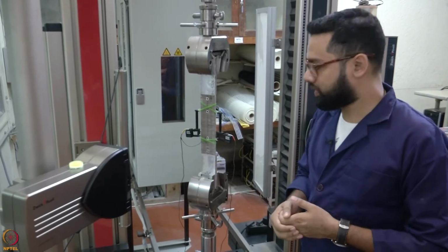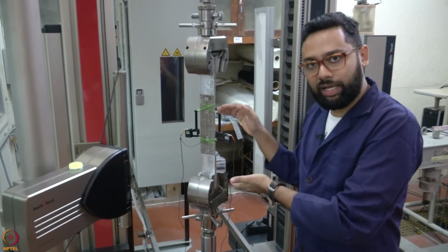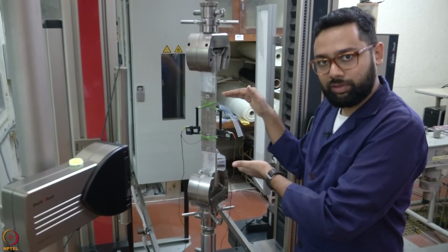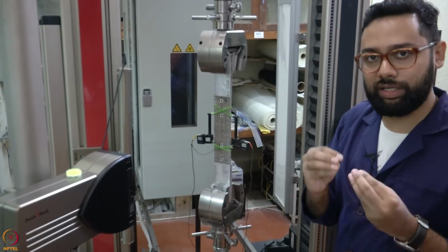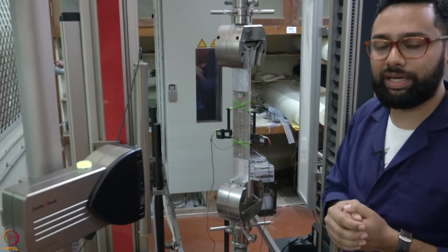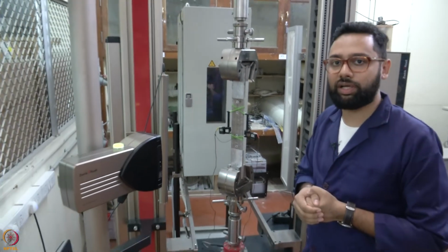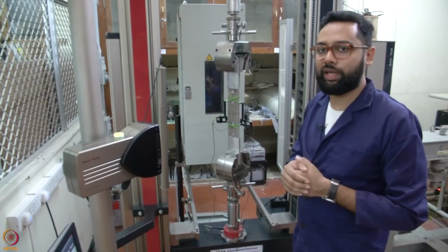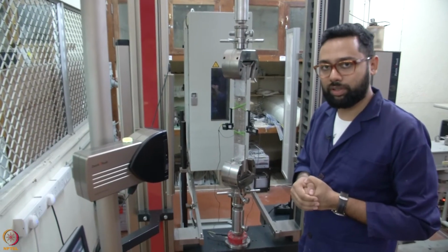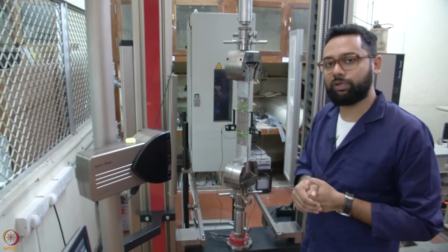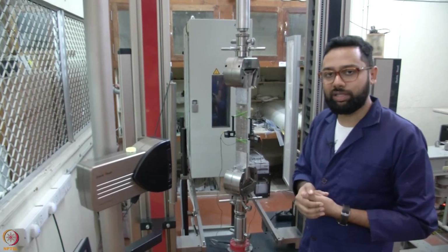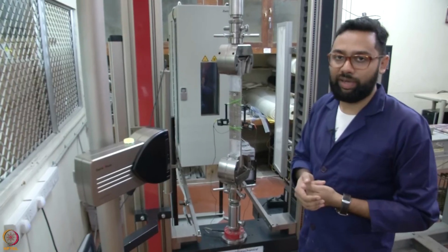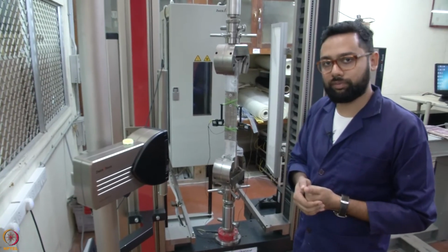The other advantage is that this material can crack anywhere in the specimen. For a contact type extensometer, when you have a crack near the extensometer, it causes distortion in the readings. This can be avoided in the case of a video extensometer. Also, for a material like textile reinforced concrete, you will have multiple cracking happening in the gauge length, and that can be very well captured by the video extensometer.